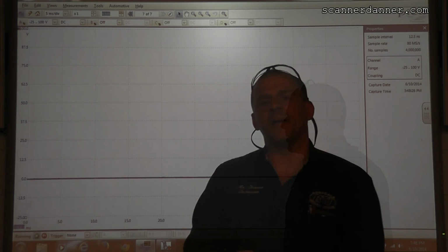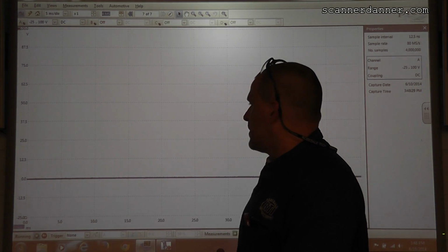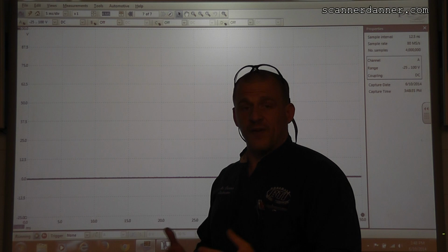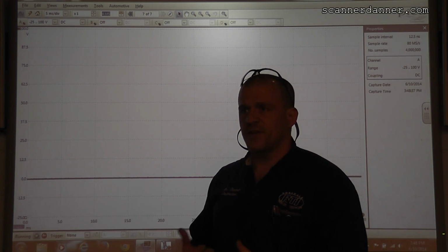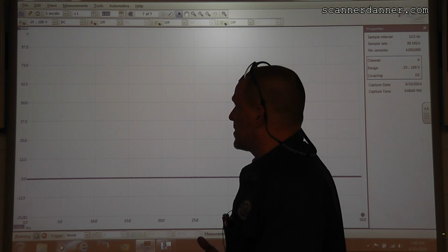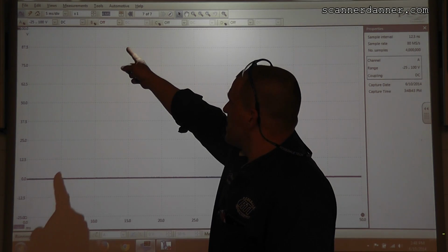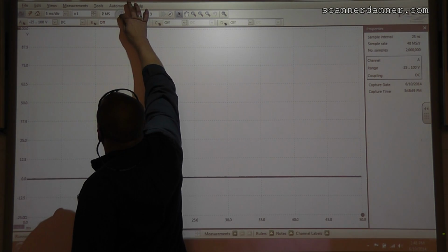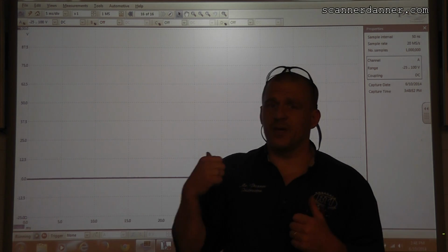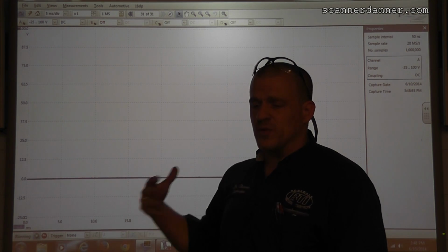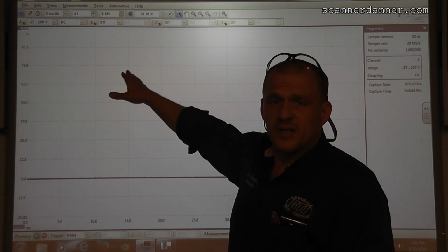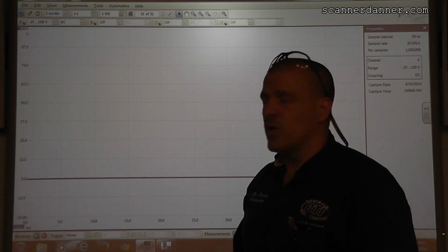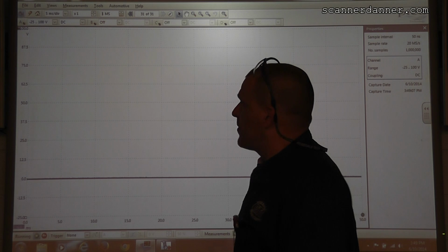Okay, now let's talk about the time and how the time relates to this. I think the best thing I can do is show you a live coil firing event. I have a vehicle in here and it's set up for that. Let's see if I can introduce the time part for you first. Our time, this 5 milliseconds per division, is my setting right now. Let me drop my sample rate back to this 1 megasample setting. And by the way, on the Pico, it's a pretty good default. In fact, when you load the tool, it's set at 1 million samples. For the most part, you're going to be fine leaving this one alone. There are times we want to play around with it.